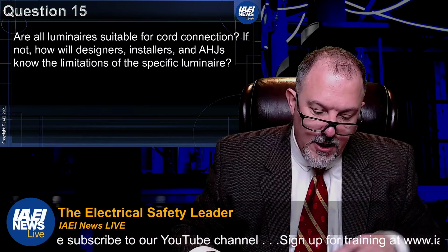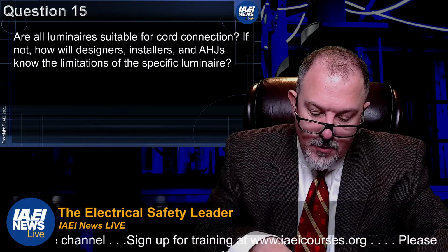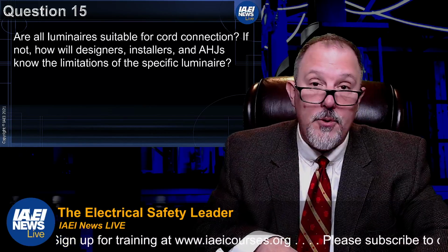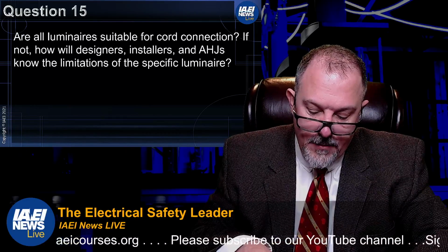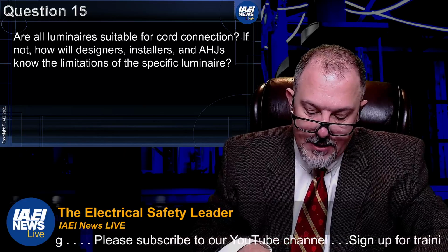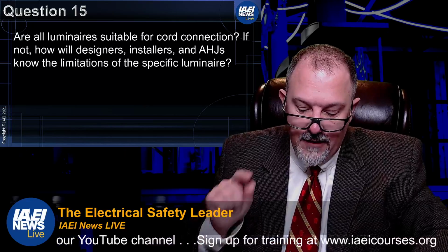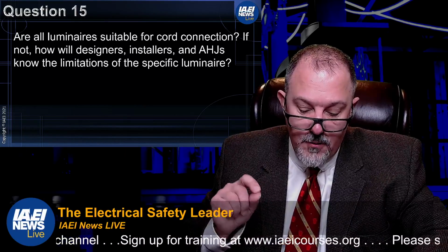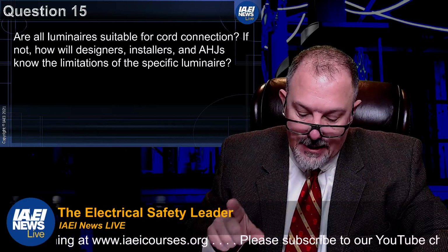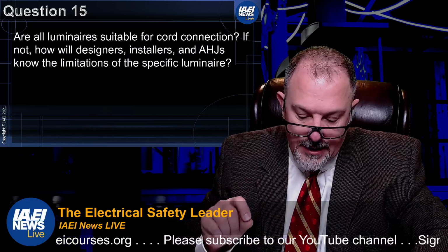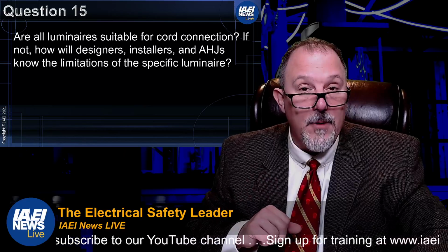Cord-connected lampholders and luminaires, 410.62. Where a metal lampholder is attached to a flexible cord, the inlet shall be equipped with an insulated bushing that, if threaded, is not smaller than trade size 3/8 inch pipe size. The cord hole shall be of a size appropriate for the cord, and all burrs and fins shall be removed in order to provide a smooth bearing surface for the cord. Bushings 9/32 inch in diameter shall be permitted for use with a plain pendant cord, and holes 13/32 inch, 11 millimeters, in diameter with reinforced cord.